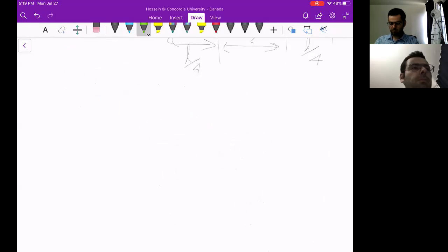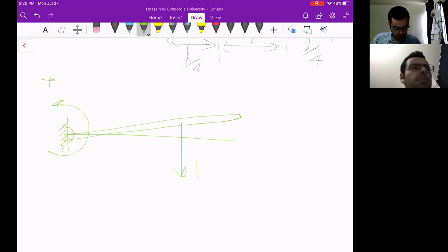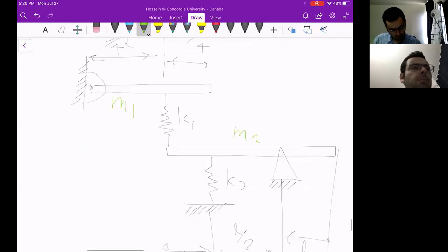So if I displace the rigid bar 1 upward, with counterclockwise considered positive, the spring will oppose the motion, and the spring force is nothing but K 3/4 L theta 1 minus 3/4 L theta 2, because the spring is connected between the two and there is a relative motion.